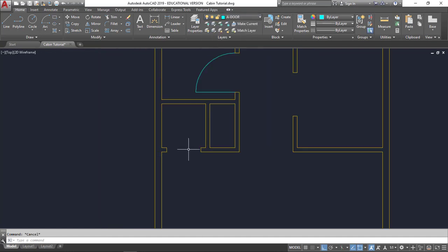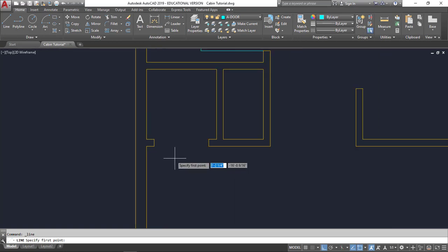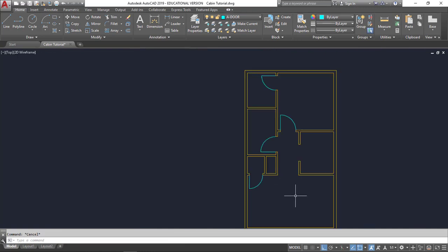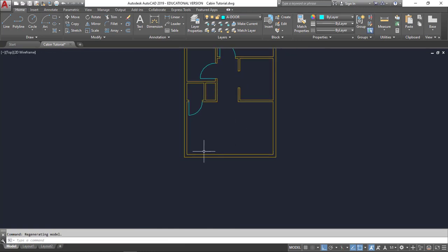And this one's going to open out into the room since it's a mechanical area. I'm going to select line. It's going to be from here, and I said that was 2'4", so 2 foot 4 inches. Escape, and then my arc, start, center, end. Again, I want to go counterclockwise, so start at this point, go to here, go to here. And I have 2 more things to do.